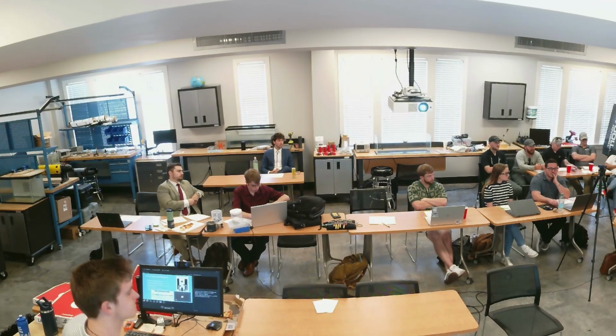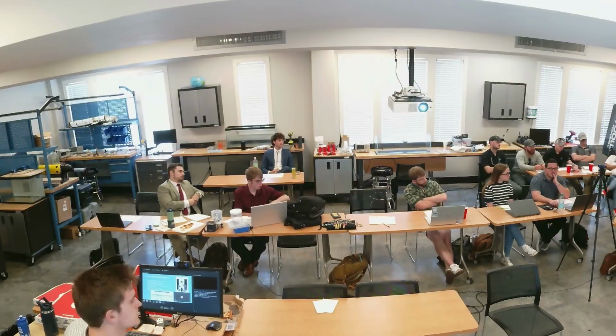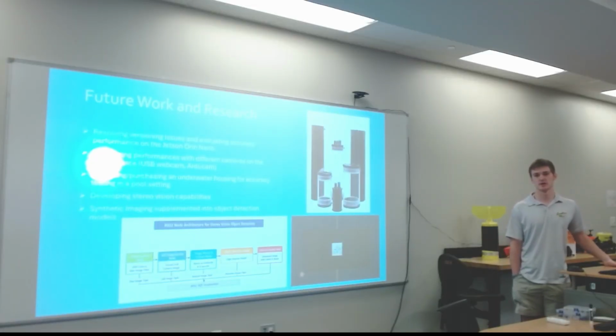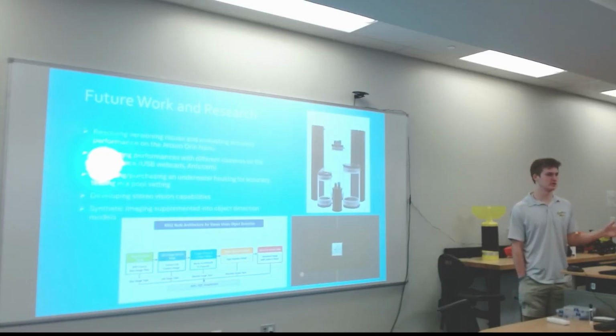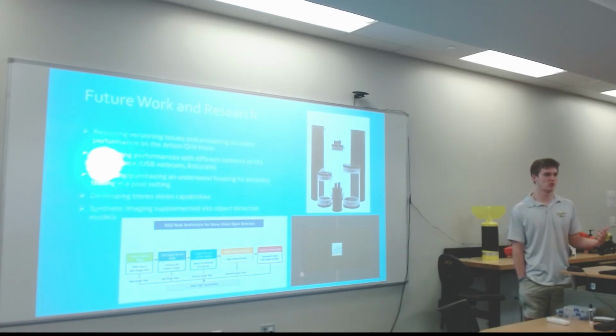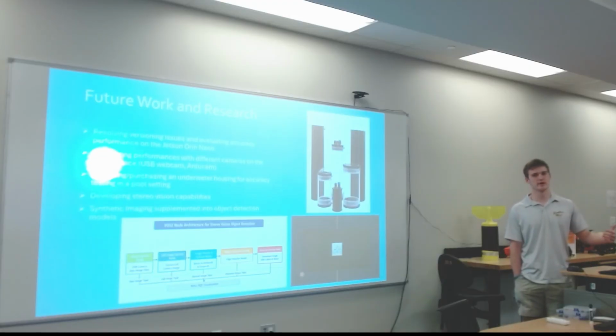Kind of related, I think you looked into image augmentation. Yeah, so Edge Impulse already has a setting for image augmentation. Essentially the color, slight angle adjustments, and different slight changes like that to the image quality are augmented by the system. So that's something that Edge Impulse does, but you certainly can do that on a larger scale for similar reasons to what they're saying.